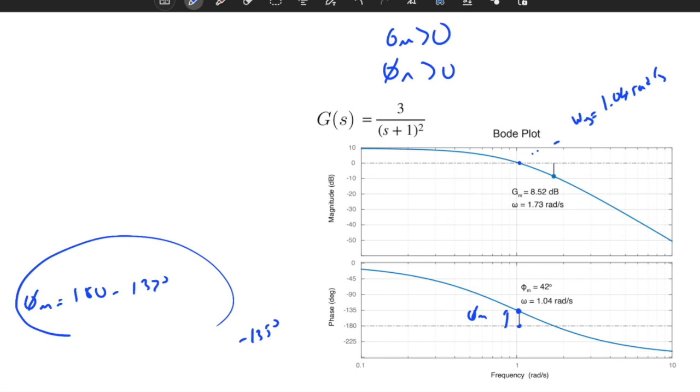That's nice. So let's assume that I change the gain without changing the phase, which I can do by technically shifting the Bode plot. If I add a gain and technically increase the magnitude plot, let's make it worse: I shift it such that it crosses the 0 dB line here.